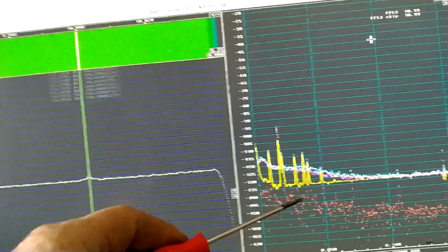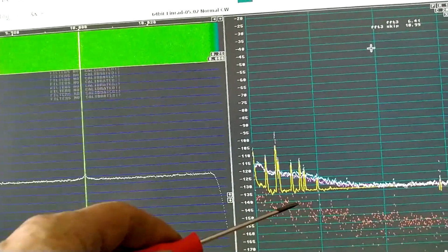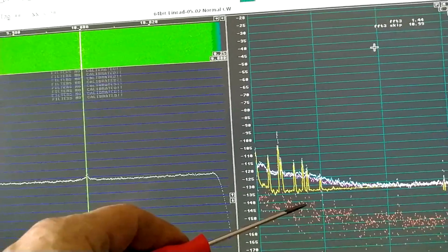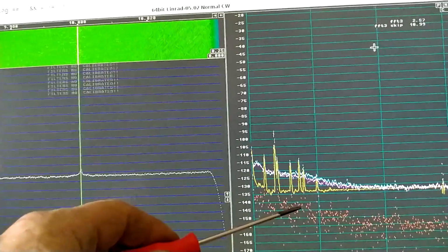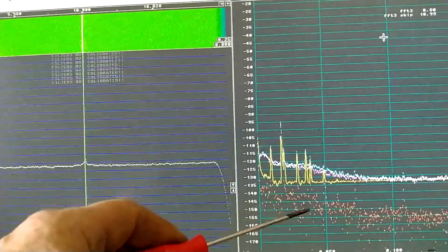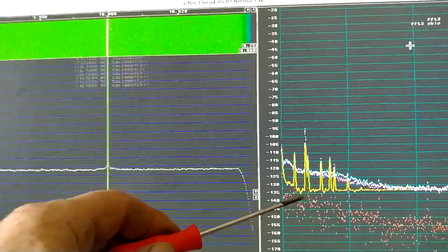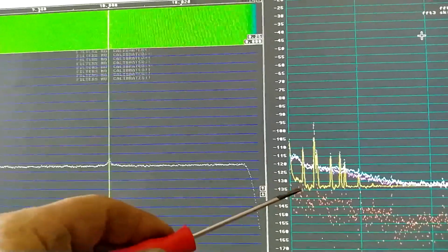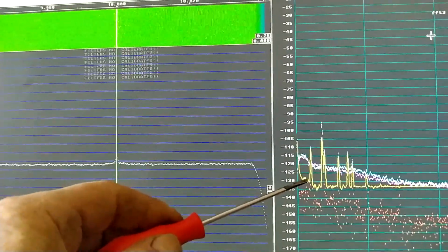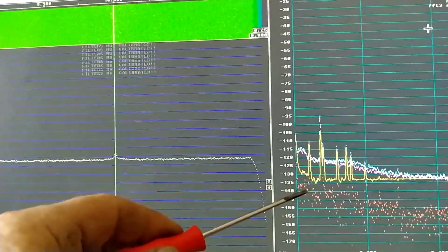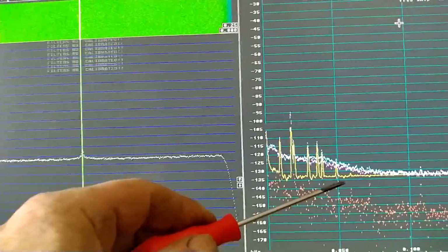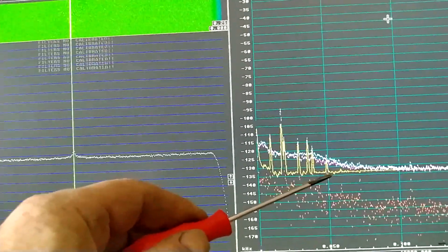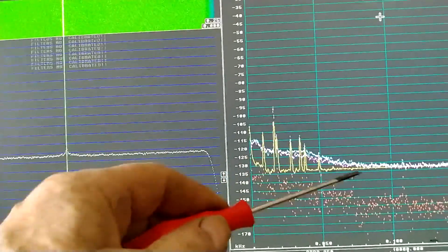It is in 90 degrees with respect to the common noise between the two channels. So this is an artifact of the hardware. And there are spurs, that's not really a problem. But here there is something added in phase, and the imaginary part is almost equally strong. So down to maybe 50 Hz, this is a reasonably reliable result.